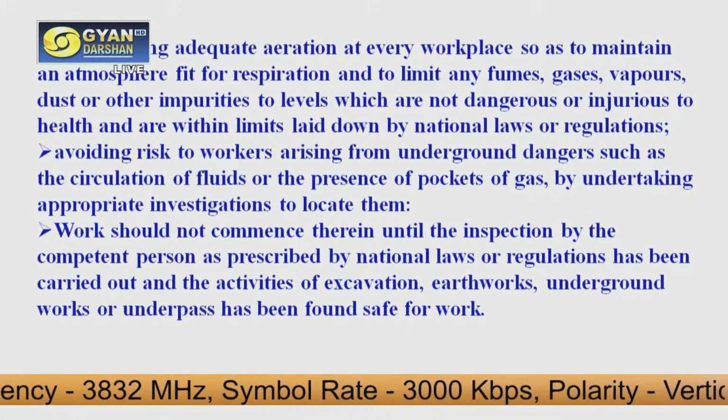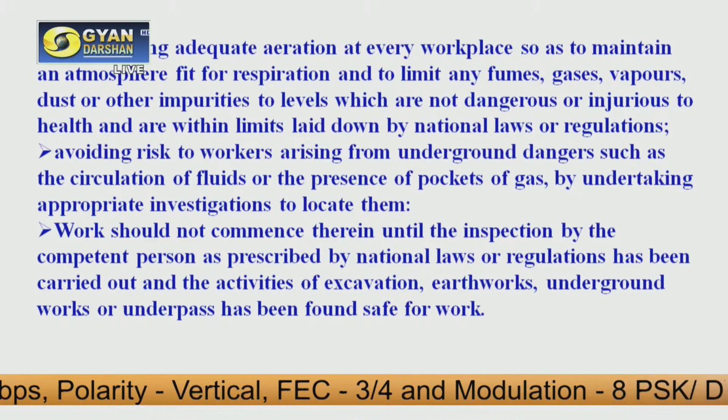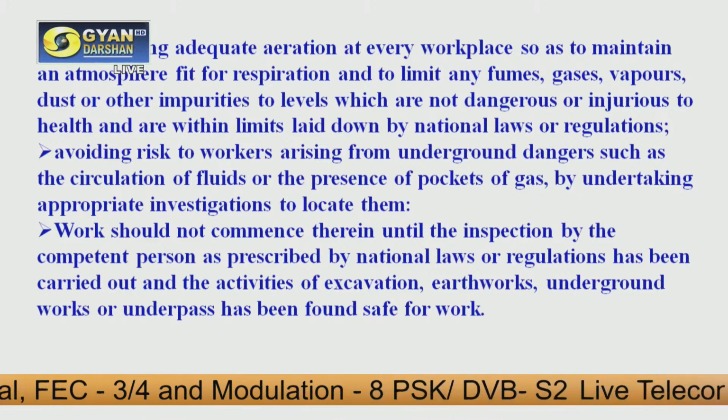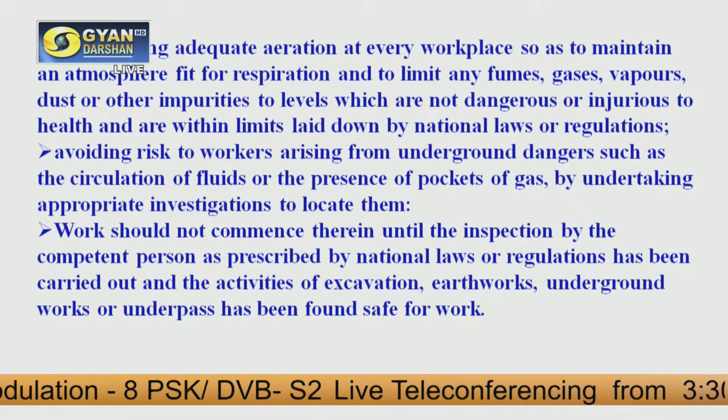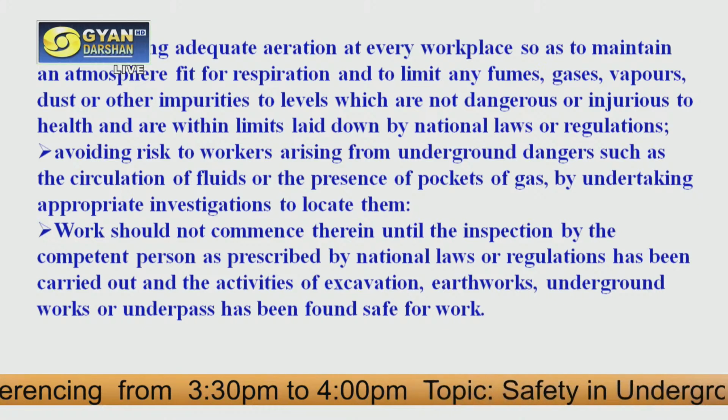Then work should not commence therein until the inspection by the competent person as prescribed by the national laws or regulations has been carried out and the activities of excavation, earthworks, underground works or underpass have been found safe for work. Means workers should not be allowed to start work until that work in underground conditions is safe. Only after ensuring that the place where these workers are going to work is safe, it is not having some water pocket, it is not having some gas pocket or some other dangerous material or harmful material in that condition basically. So we have to inspect that.